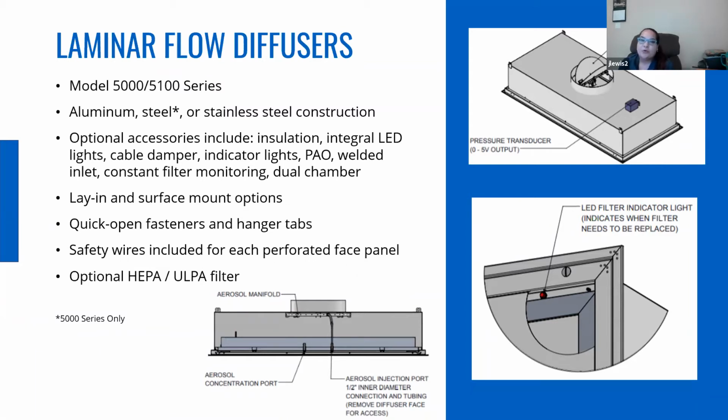You can see that in the top corner, the butterfly cable operated damper, and that is accessible from the face with quarter turn fasteners. You can remove the face and get access to your HEPA or your butterfly damper, or anything you need, you can have room access to. And that goes for the LED driver box and all that as well.